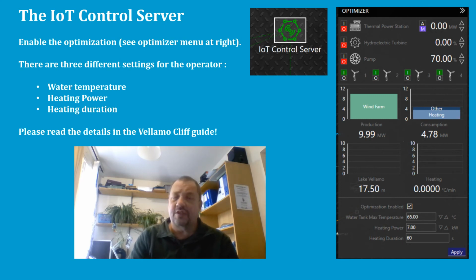When the set point is 65C, 149F, then the houses in the first half of the vector V will receive a switch heating on command, and consequently the rest of the houses in vector V will receive a switch heating off command. When the set point is 75C, 167F, then all the houses in vector V will receive a heating on command. The number of houses receiving a heating on command will be interpolated linearly for set points between the min and max set point value of the tank temperature.